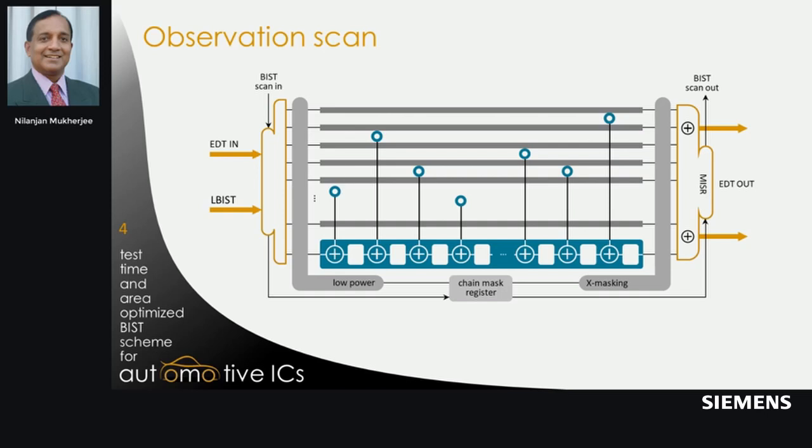One of the questions that arises is, how is the scheme different from techniques such as circular BIST? There is a fundamental difference between the schemes. In circular BIST, the scan cells were not only capturing responses, but also driving combinational logic during shift. This creates a sequential dependency between subsequent shift cycles, thereby making the fault simulation extremely complex. In the proposed scheme, the observe points are only observing the test responses and don't provide any stimuli to the combinational gates. This reduces the complexity of fault simulation.